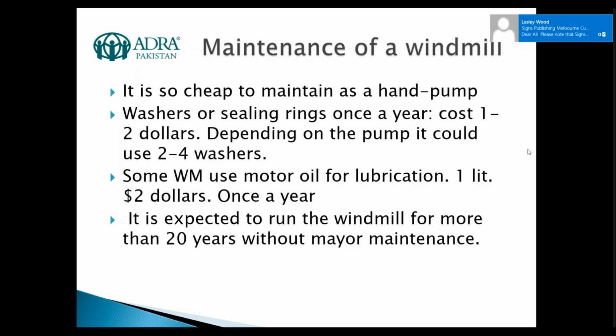But if the material of the tower or the propellers is not galvanized or protected against rusting, you can paint every 5 years maybe, depending on the paint that you are using. We saw windmills more than 20 years old without any painting. Okay, in some parts there was rust, but not much. But the maintenance is very, very low cost, no matter the material.